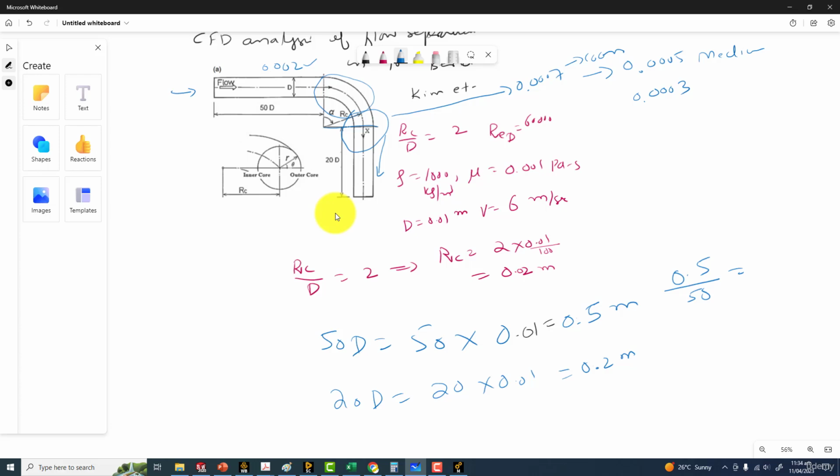And also on this face, I'm going to provide the same sizing 0.007 for the coarse mesh. And for inlet faces and outlet faces, I will provide the same size, 0.007. And I'm going to provide the number of inflation layers for the coarse mesh, the boundary layer which is normal to surface, 20 layers.